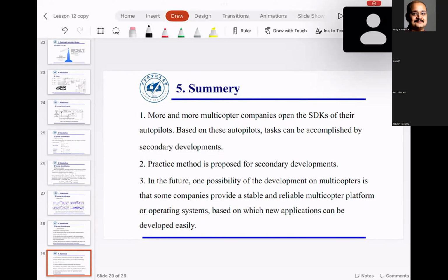But the assumption is that we start with a linear system. With a linear system, even though the initial conditions are different, the behavior is fairly predictable. So we start with a linear plant model, improve on it, and then test that plant model and the controller for a variety of initial conditions and make sure that the system is responding the way we want.